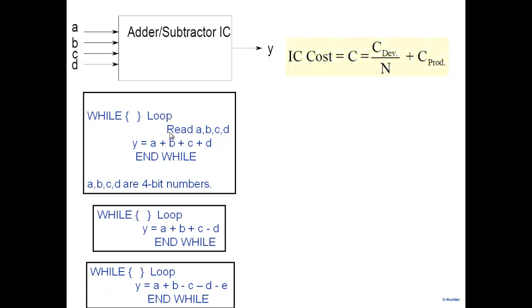Now we have discussed this, that when you want to design an IC, the cost of an IC, you can break it up into two parts. One is the recurring cost. Every time you fabricate, you have to use a wafer. You're using a part of a wafer, and so there is a die cost, and we had seen earlier there's a packaging cost, there is a test cost. That's a recurring cost, and then there is a one-time cost, non-recurring. So production cost was die cost, packaging cost, and test cost here.